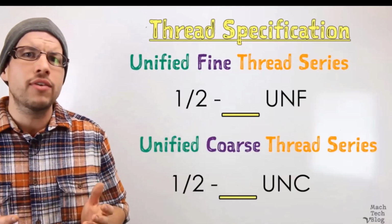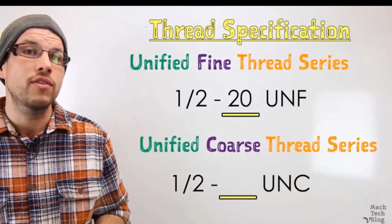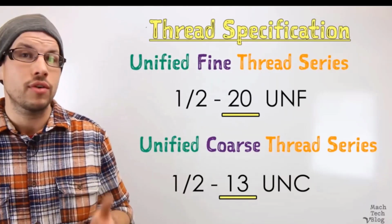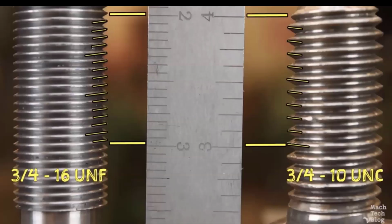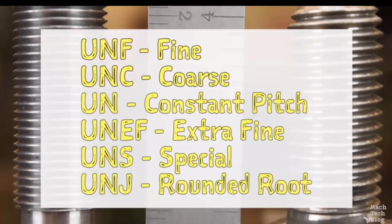For a half-inch major diameter, like our bolt, the fine series has 20 threads per inch, while the coarse series has 13. As another example, for threads with a 3/4 inch major diameter, it's 16 threads per inch for fine threads and 10 threads per inch for coarse threads. Unified fine and coarse are the most common thread series, but there are a few others as well.